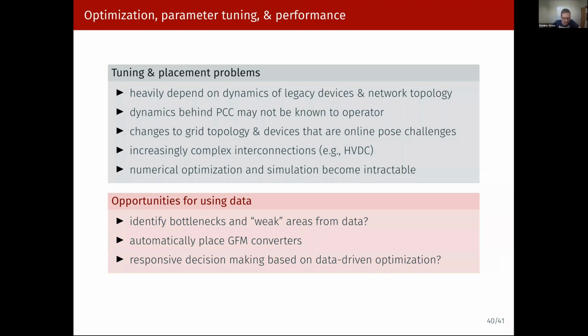And that basically goes back to that fact of, if you have these systems that use a mix of all of these technologies, as I was mentioning, the placement of some of these converters really matters, right? So you could think of using this universal control or standard grid forming controls backed by a battery. And the question then becomes, where do we put these things?